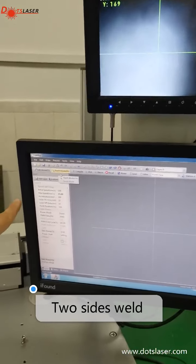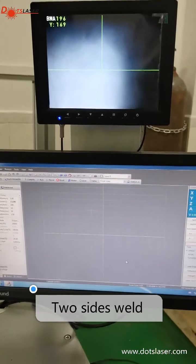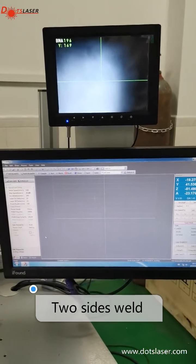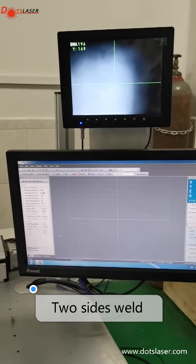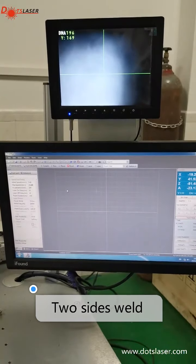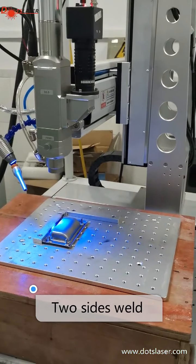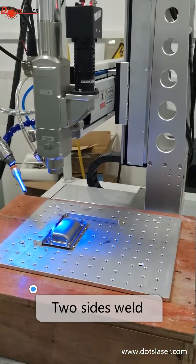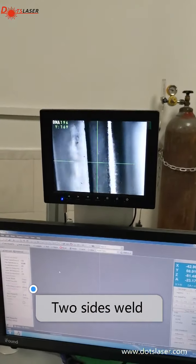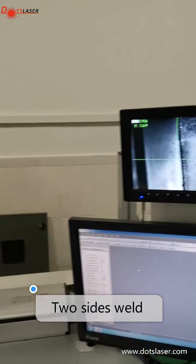So we should select the teach mode. The teach mode is for you to find the path for welding. So here we go. So we should make the line as well. Before you make the line, you have to find the focus point for the welding place. Move to X, Y to find the point. So you should, through the camera, you will see the gate of the line.